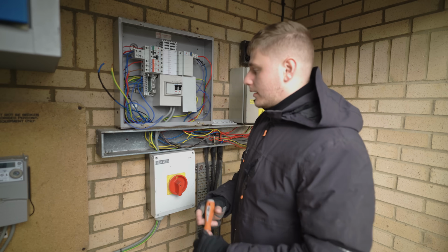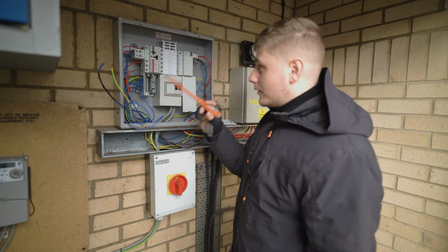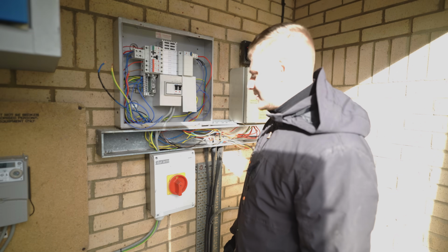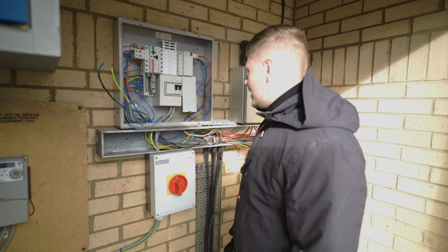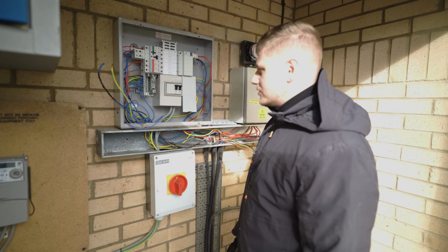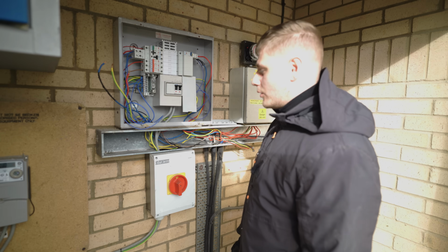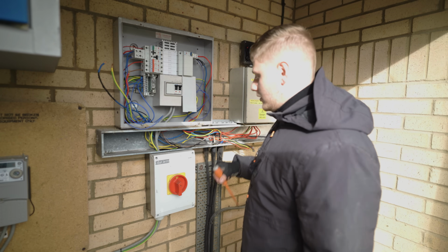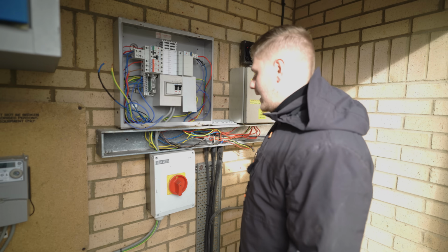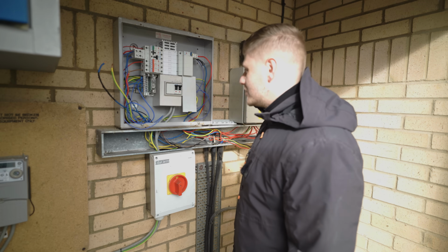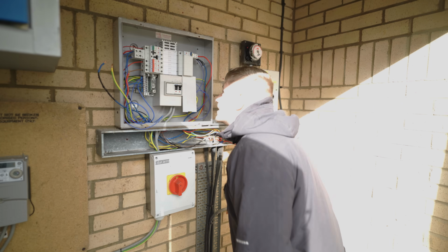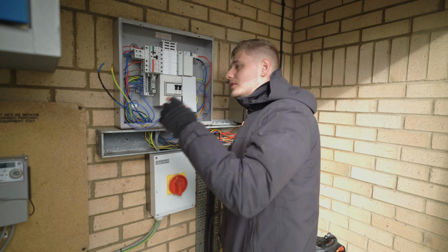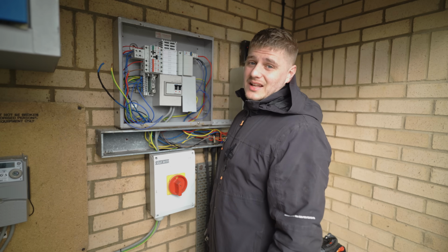And generally, horizontal surfaces of trunking and fuse boards want to be 4X, and I believe sides are like 2X, which is a lot more forgiving. But you can generally cover it by bunging holes and stuff like that. It's not that much of a big deal, but when you find older installations where the trunking looks like a Swiss cheese, you can run into IP issues. In this case, it's all pretty sweet, it's just very corroded, so I'll just note that down. I'm going to get the Q-Tech out, and we'll start seeing what the circuit's saying.